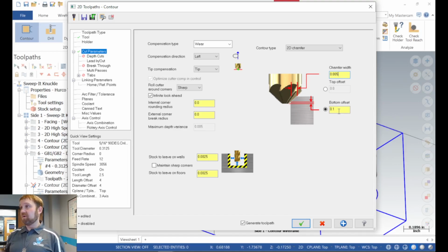I think it even says it on the print. But you might only do like a 100 thou deep pocket. Well, if you do the pocket 100 thou deep, I probably wouldn't set that to 100 thou tip comp, because then it's probably going to drag a little bit inside the pocket. I might set it at 75. I don't like to go less than 50 thou, but I will if I have to. I really don't like to go less than 50.